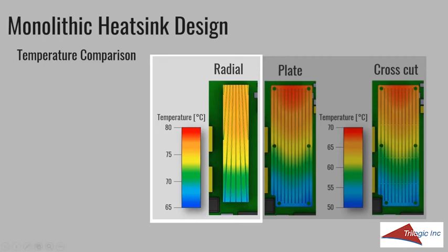But the idea behind this design was, one nice thing is it's kind of organically got less surface area upstream than downstream. So it kind of balances how the heat's going to be rejected, because you have more surface area to reject the heat down here. The other idea was that once the air enters the channel, it will accelerate down the channel, providing better convective heat transfer as you move down the channel. The third reason why this was a novel idea, in theory, was that these channels were set up in such a way that cooler air could be introduced on the sides.